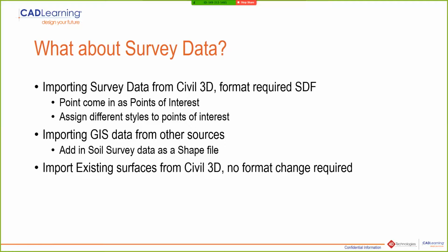There's other types of GIS data. There's a lot of options for GIS import. You've got shapefiles, SDF, DGN, there's a lot, and you'll see it in a few minutes when I show you the real thing. You can also bring in surfaces made in Civil 3D, whether that's your existing surface, your proposed surface, a preliminary, or a volume surface. You don't have to change anything.